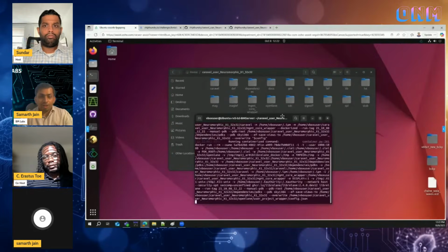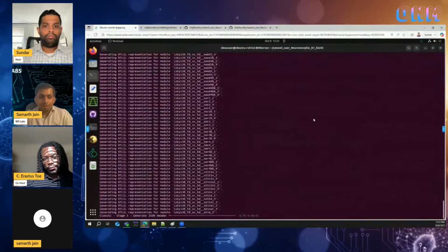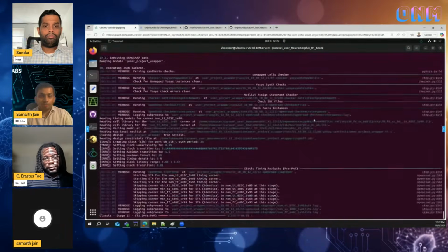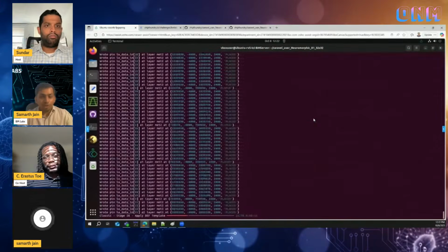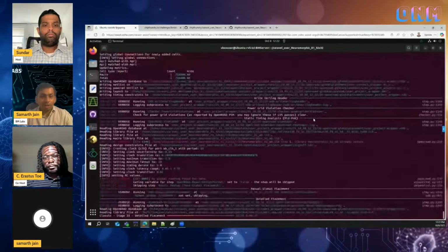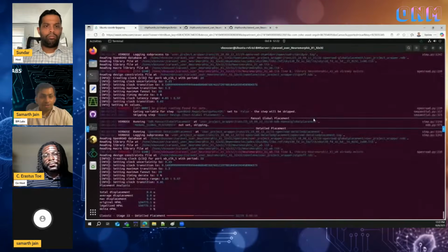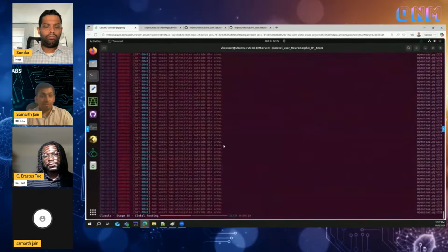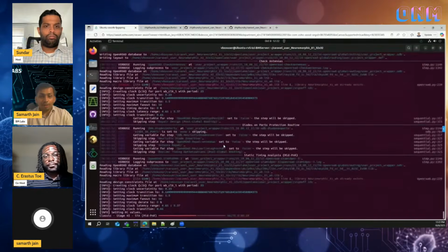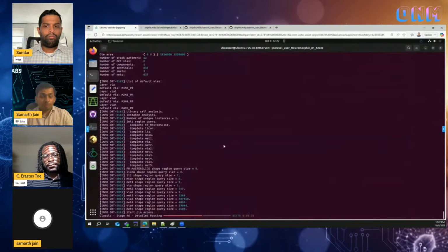So once you have done that, you can run this make command and it will start taking your Verilog code, which you generated using CocoTB, and do all the process for you, from taking your Verilog, placing it into an actual hardware, doing the timing analysis, whether your system can meet the timing constraints, right? Because there's some timing constraint provided by the Caravel harness, because you're using the wishbone interface, so you need to meet some timings. It will also do LVS checks, which is layout versus schematic, because you need to check whether all the pins are connected, there's no floating nets, things like that.